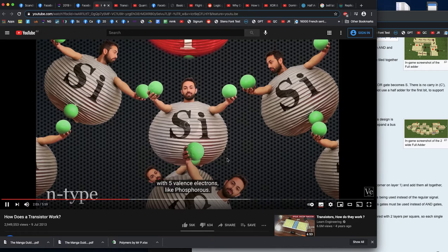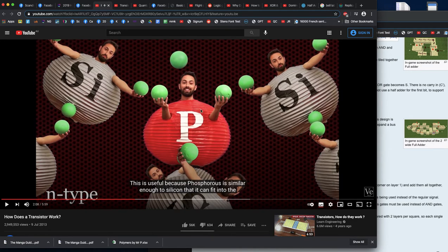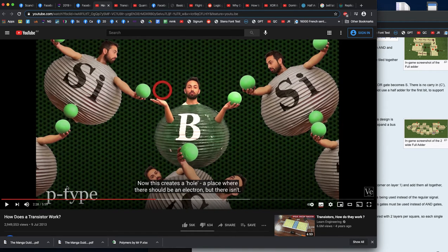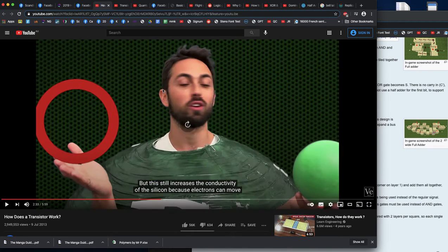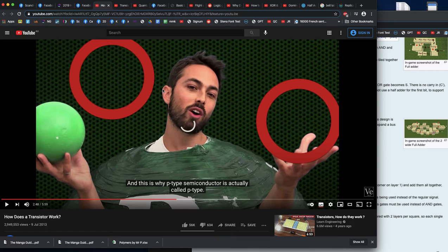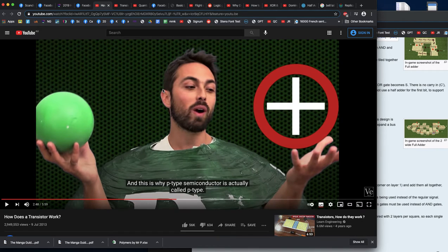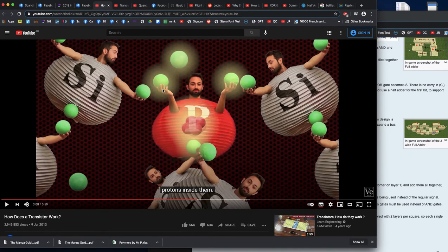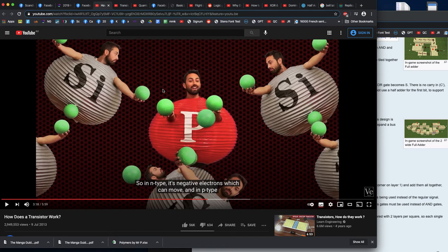To make N-type silicon. Confusingly, they're adding phosphorus, but phosphorus gives you an N-type, and they're adding boron to get a P-type. The idea is that boron has one less electron, which we call a hole, and phosphorus has one extra electron, so it has an excess of electrons. We can talk about holes moving through the lattice, or we can talk about electrons moving through the lattice. Doesn't really matter which one we use. Well, it does matter, but for the moment they're both important.